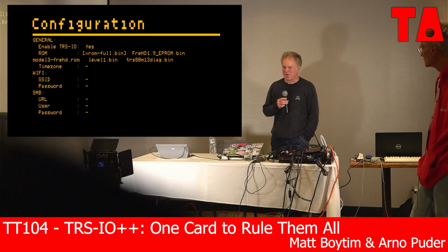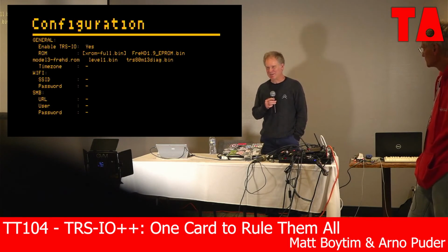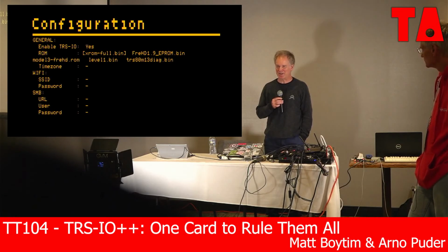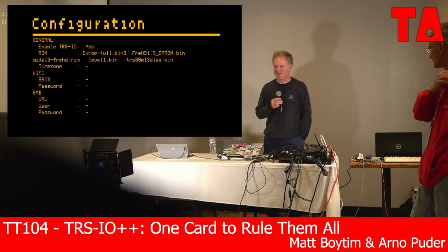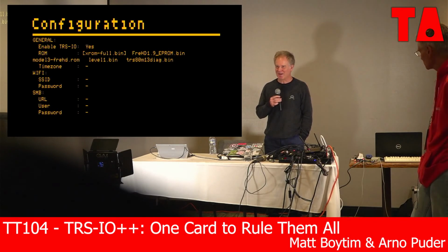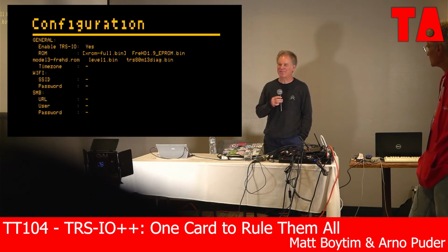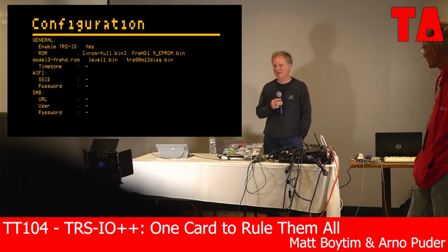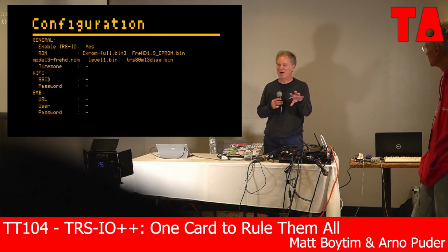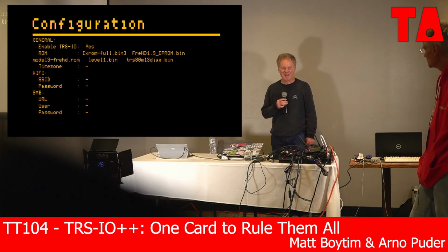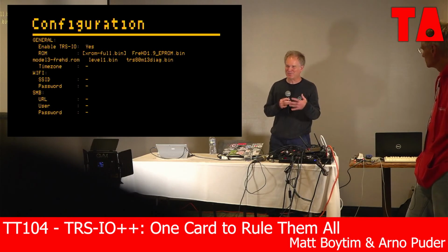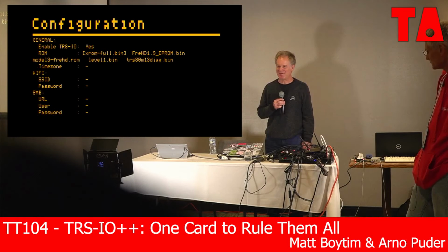Well, the ESP32 is more than just a CPU, the dual core thing. It has a lot of different I/O adapters, and the Wi-Fi module. So I think you would have to replicate quite a bit on the software side. Plus, it has 4 megabytes of PSRAM. So I think that is also why the Pocketress UI that you just saw at the end, I wouldn't even think of how to replicate that on the FPGA side.